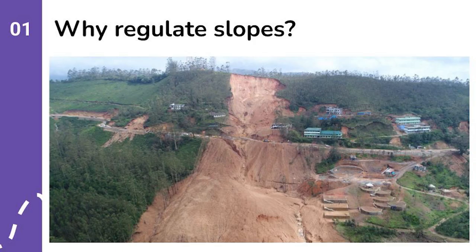But to ensure safety and environmental protection, laws sometimes prohibit development on slopes above a certain gradient. In the state of Goa, for example, since 1997, we were the first place in India that banned development on any slope steeper than 25% and needed strict permission for any construction on slopes steeper than 10%.